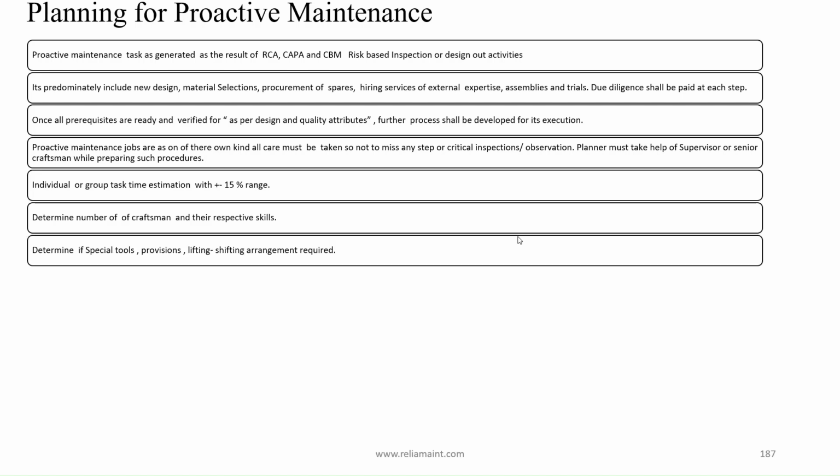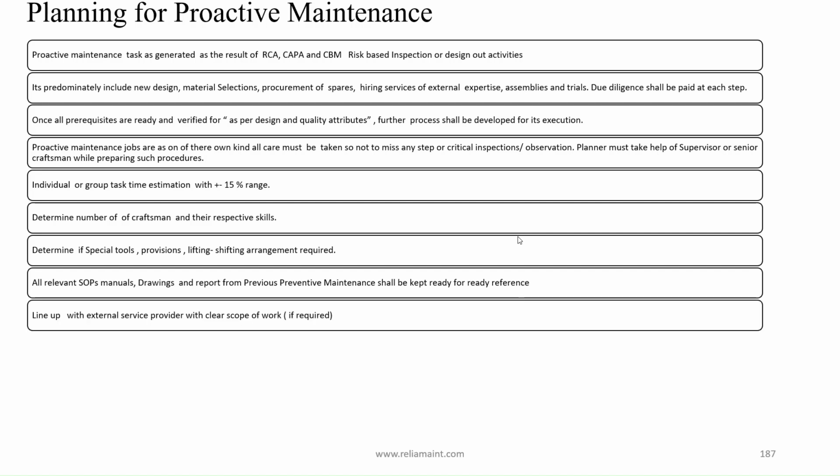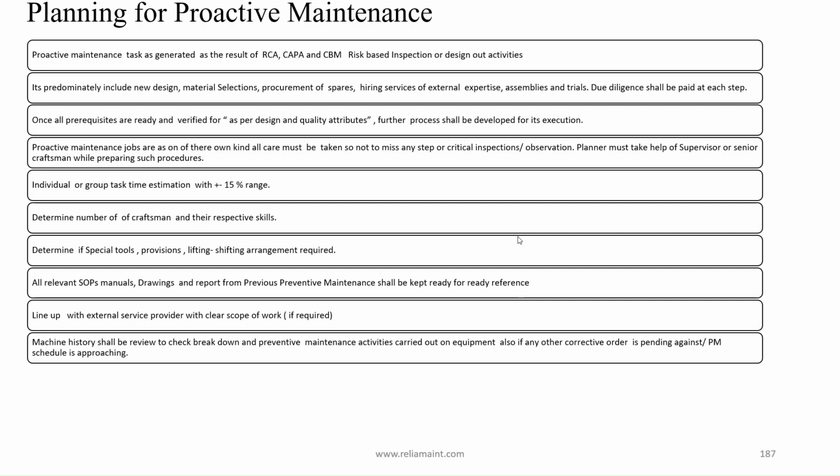Individual or group task time estimation with plus 15% range. Determine the number of craftsmen and their respective skills. Determine if special tools, provisions, lifting, or shifting arrangements are required. All relevant SOPs, manuals, drawings, and reports from previous preventive maintenance shall be kept ready for reference. Line up with an external service provider with a clear scope of work, if required.